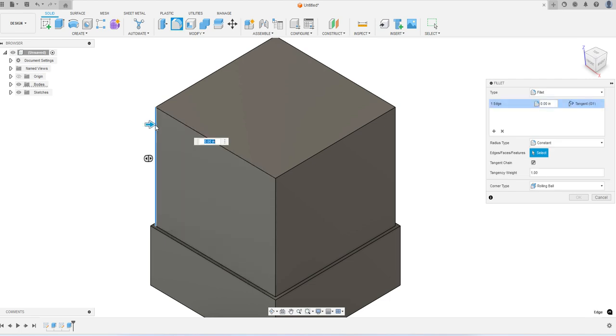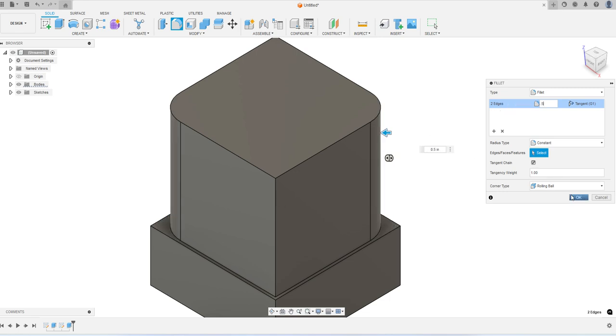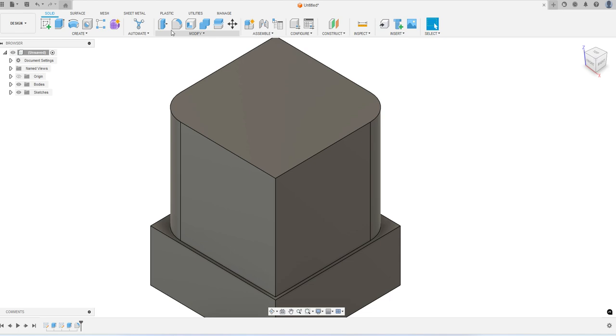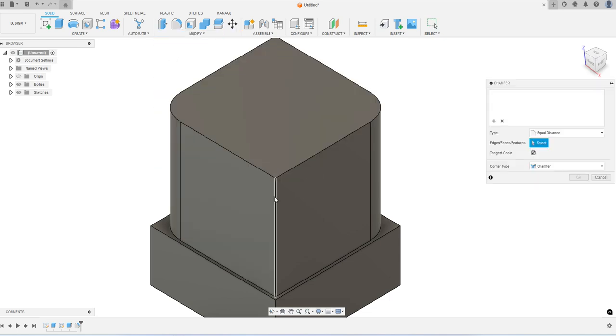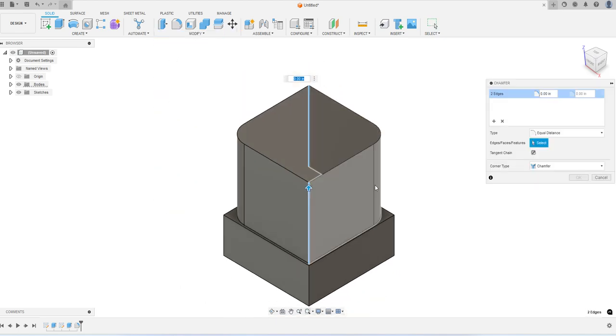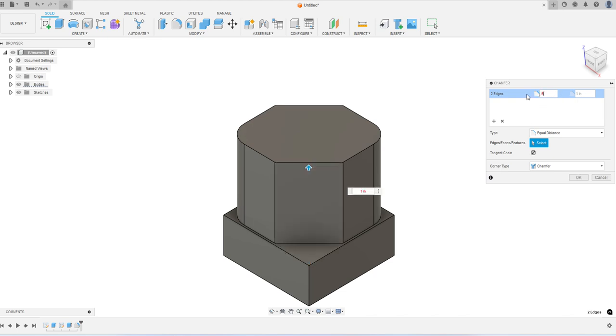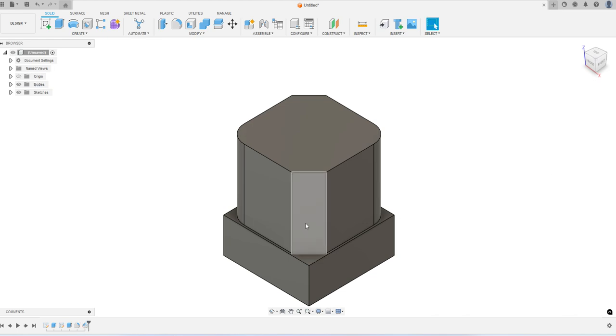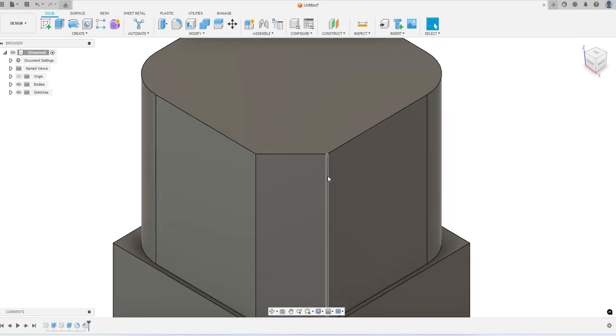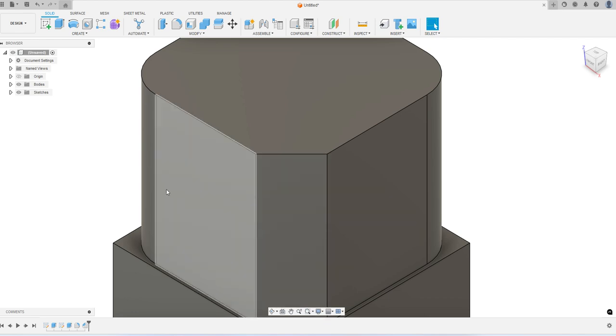From there, we can make some changes to this. Often I'll add in a fillet. With this particular one, I'm just going to add in 2 fillets, and make them a certain size. Then for the other 2 edges, I'm going to show a chamfer, mostly because I just want to show you what's possible. So you could have all 4 corners be this. They could be square. You can round them with fillets. The outer shape really doesn't matter. So having this hard edge right here is okay because it's on the outside.